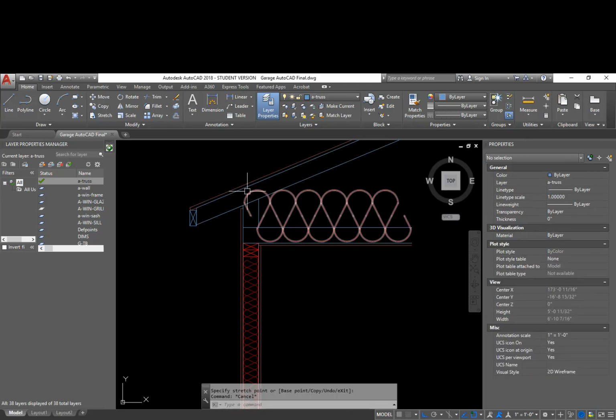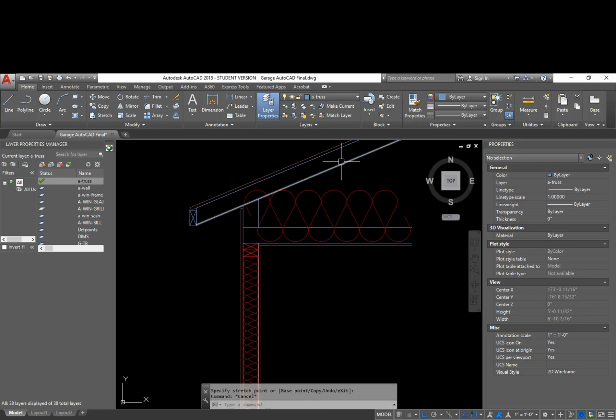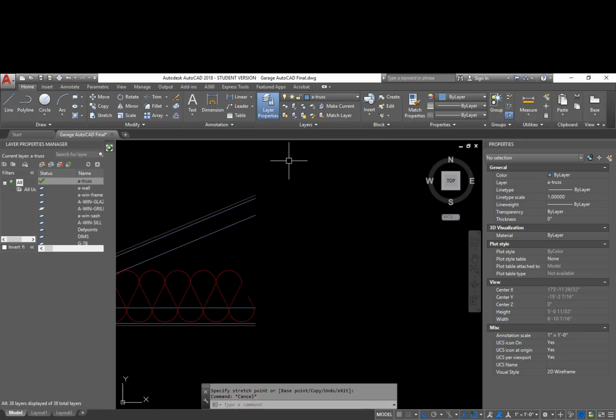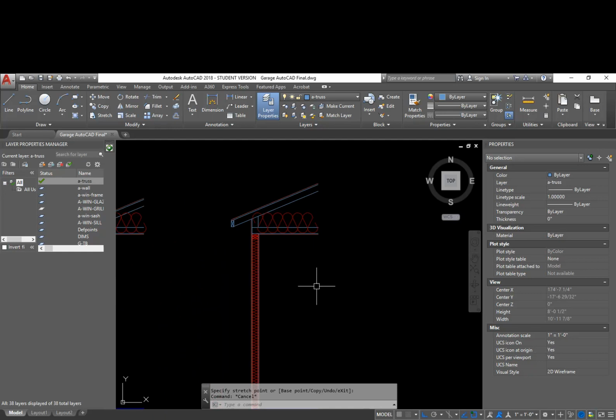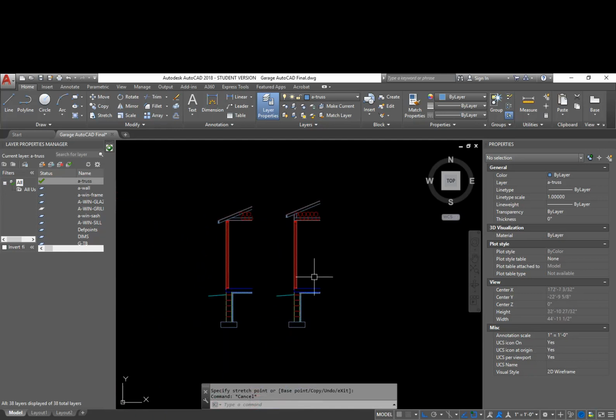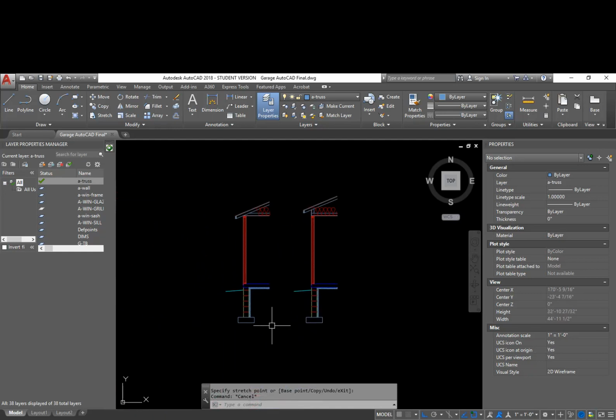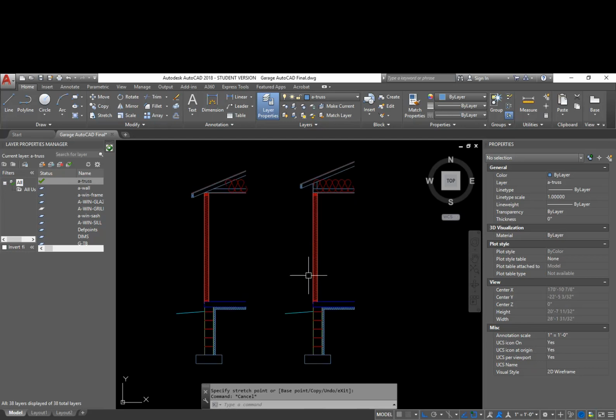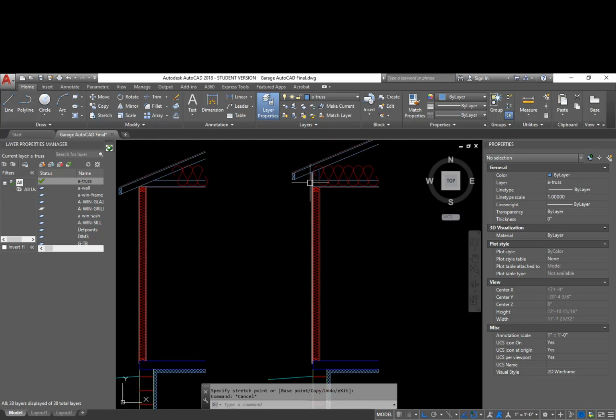And I also have about an inch here for an airspace. So I have a vented soffit, basically a vinyl soffit that has holes in it. The air moves up through here, goes through the cavity, and then exits, keeping the roof cool. So this is a pretty good situation. It does add cost to the building. It adds cost to the trusses, plus you have to have OSB that is longer than 8 feet.